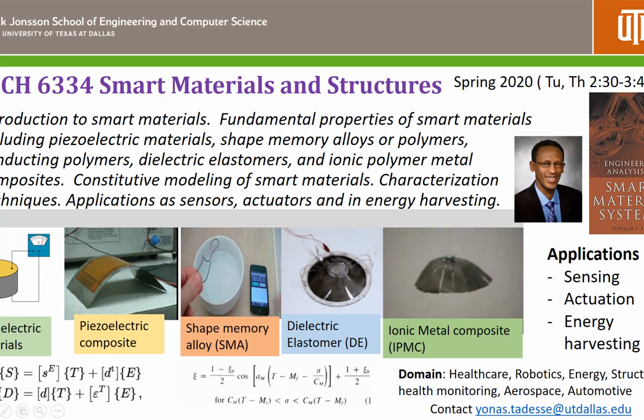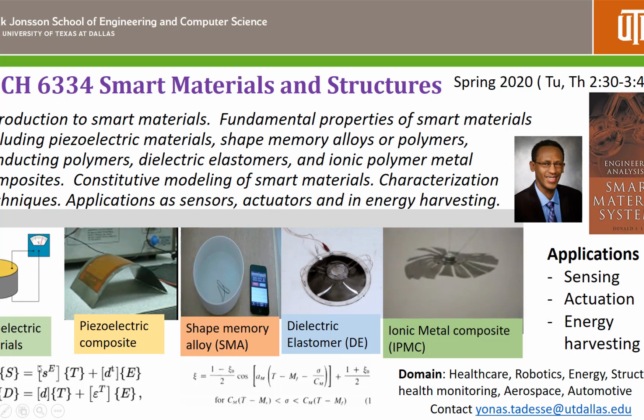And what you see here is that we'll describe the properties of this piezoelectric material using constitutive modeling. Okay, this is based on what you know before. For example, S is strain, s is compliance, the inverse of modulus, T is stress, d is the piezoelectric coefficient, and E is the electric field.